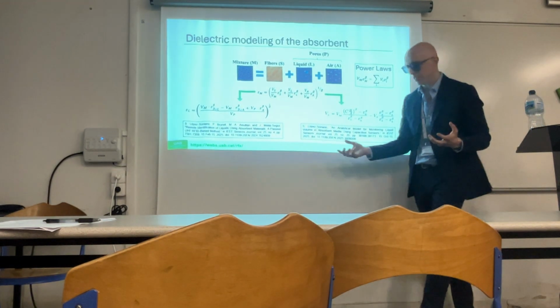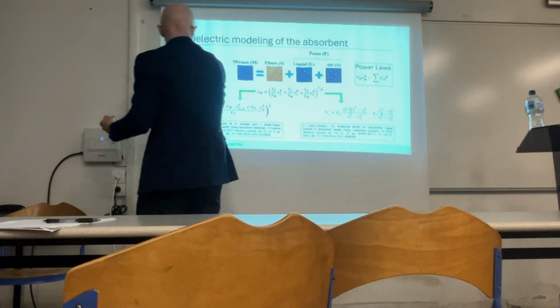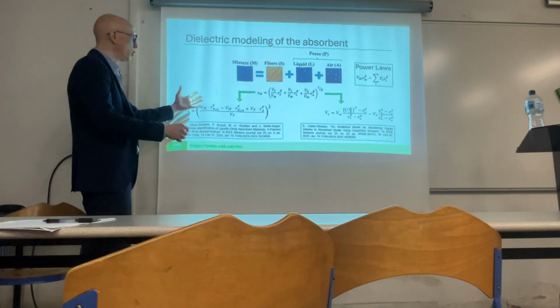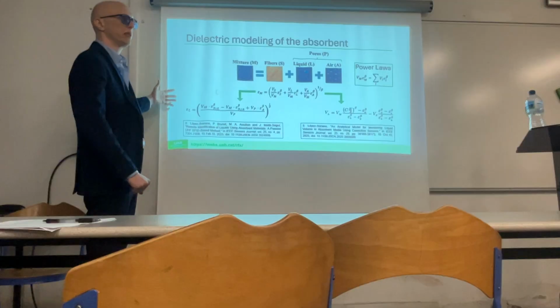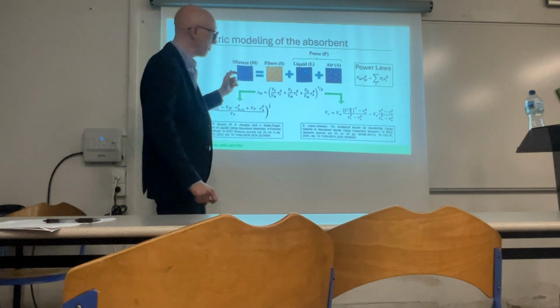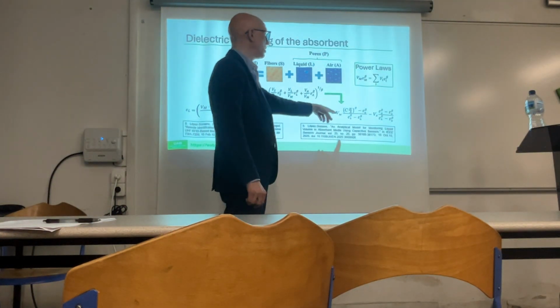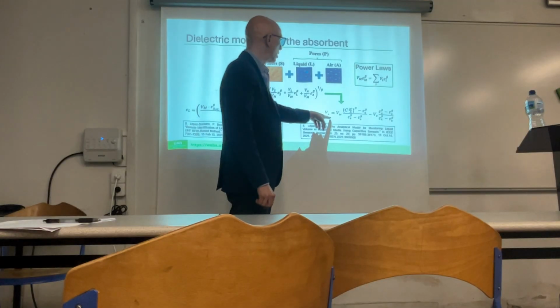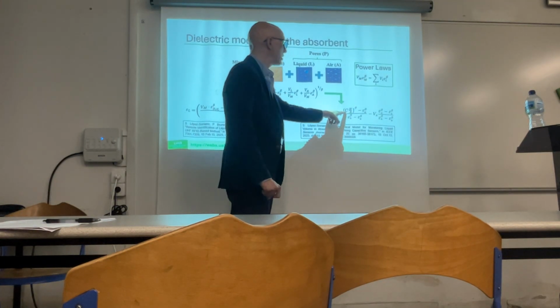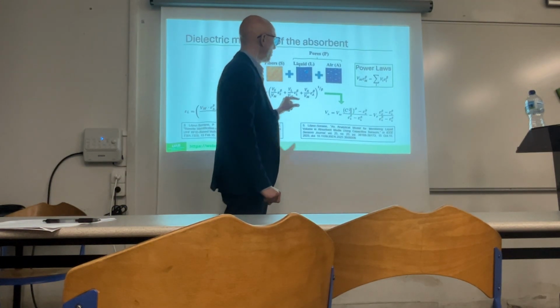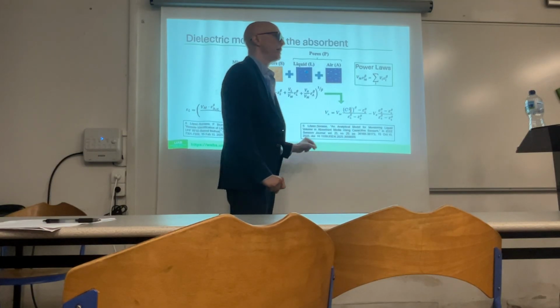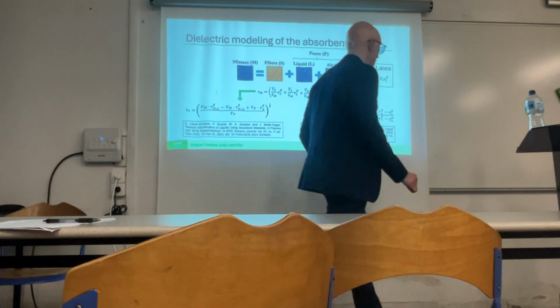So it allows us to compute the liquid permittivity, for instance, for identification of liquids in different applications. But also, we can use it in capacitor sensors to compute the liquid volume using the mixture permittivity given by the parallel plate capacitor formula.